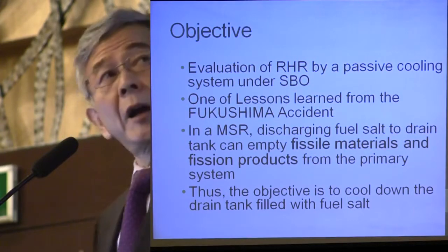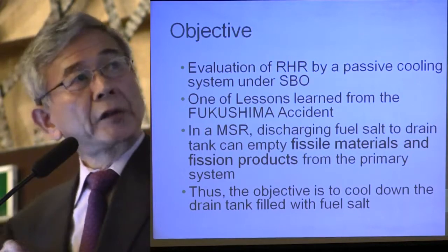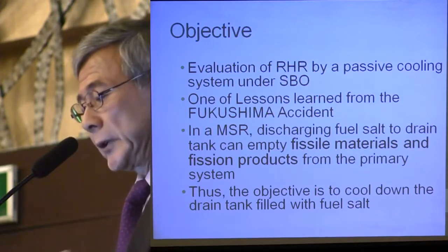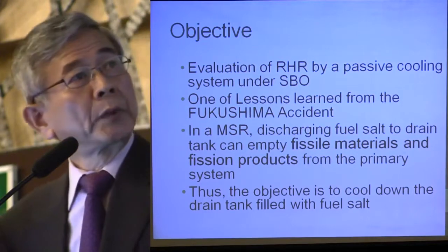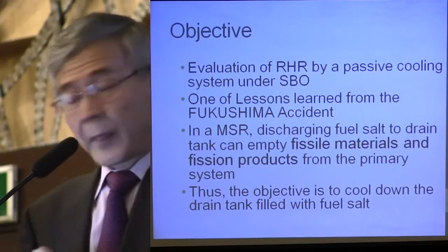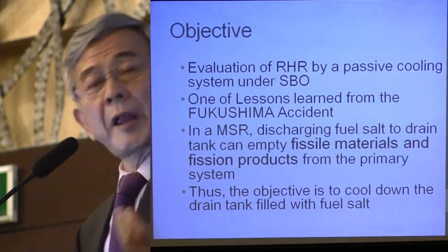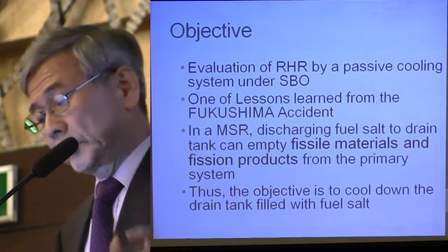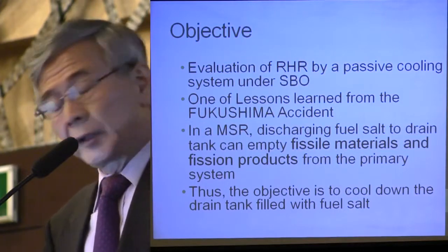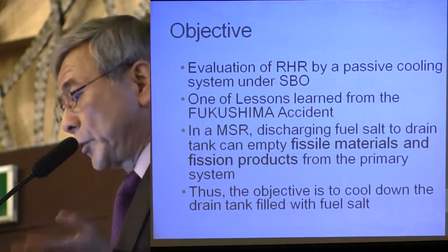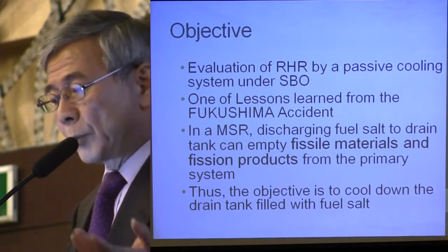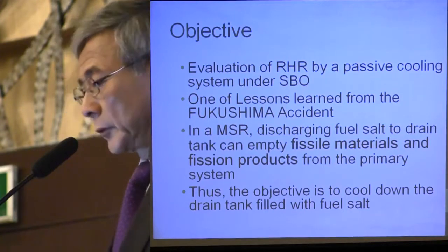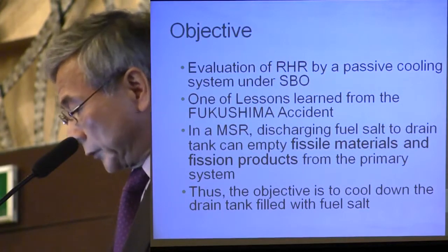And in our MSR, discharging fuel salt to the drain tank can empty the fissile materials and the fission products from the primary system. Then, if we can maintain the integrity of this drain tank, that means if we could succeed in the residual heat removal, then the whole plant can be maintained safely. This is our objective of the design study.